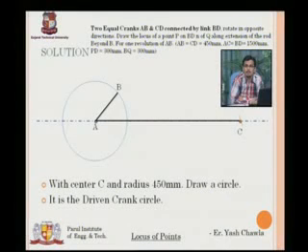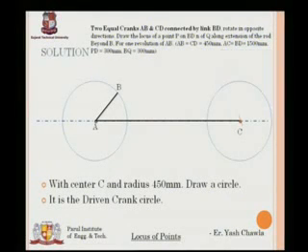C, and I will draw the crank circle through point C. Okay, now I have the reference circle on which the position of the crank will lie. So now again, with radius equal to 1500 mm, that is my length of BD, I need to mark D. 360 degrees are there on the circle with center C.